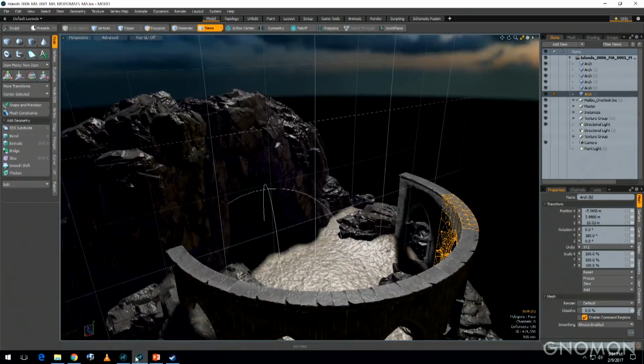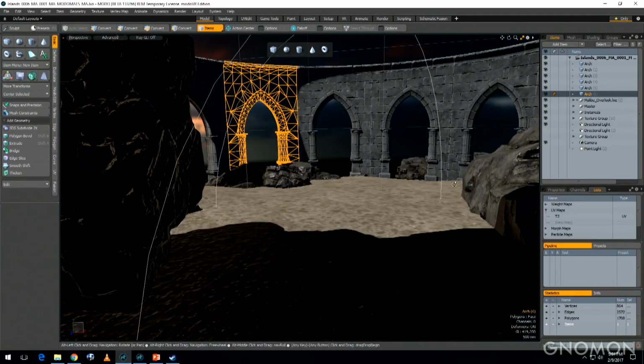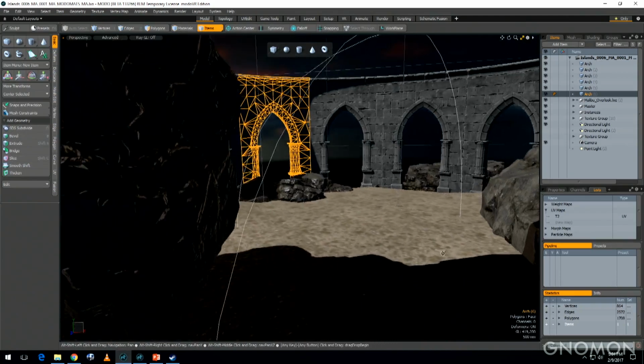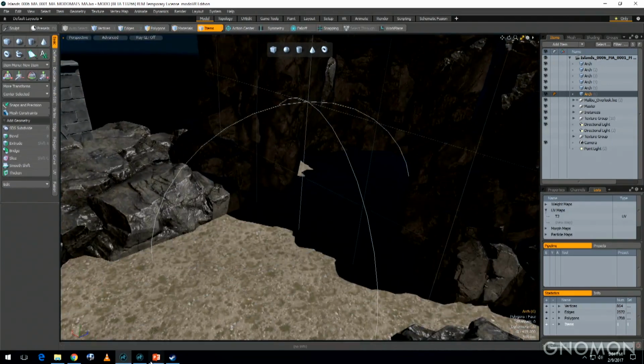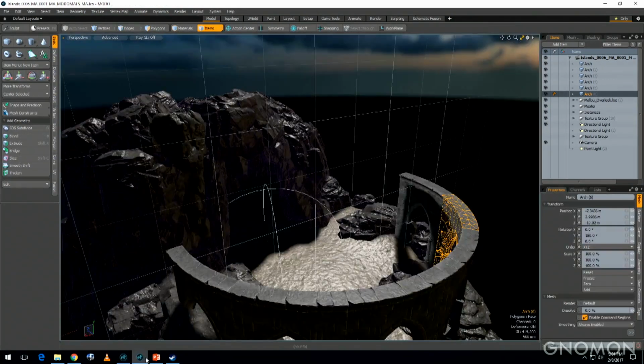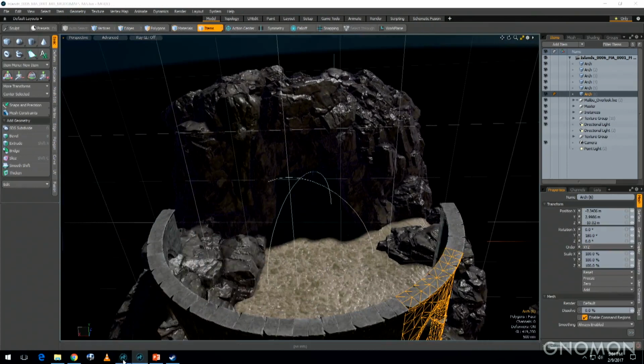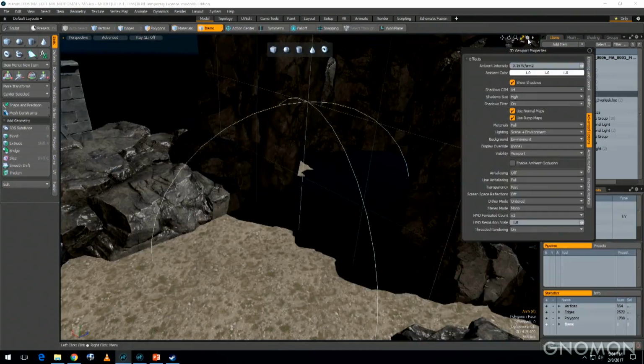And if I hop on over into the Modo VR build, just VR research project, I can take a look at the improvements. You can see if I come out here and take a look at the cave, shadows are dramatically improved. And now that is because we now have cascade shadow maps. So if I go ahead and pop this on open, you can see we can choose the number of cascades. We can choose the actual shadow size itself. So a lot more control over the quality.